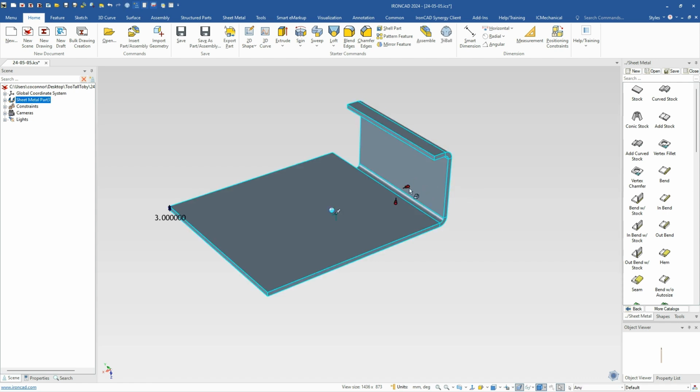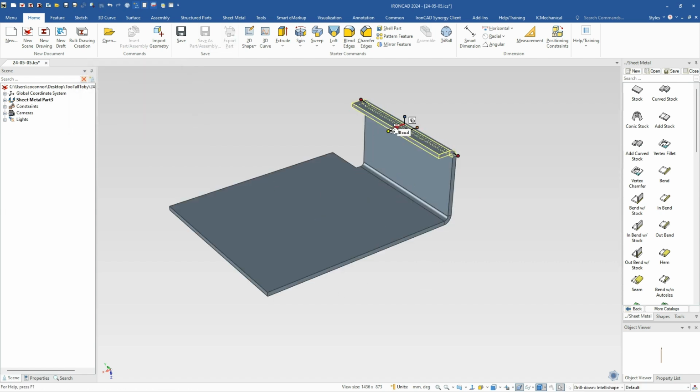It can modify these. So in our case, we want to edit the distance from this guy to the point, which is the midpoint here, and we know that has to be 80mm because it's going to be 160 total in the distance. So now we can come up to this handle, get its value again, same thing, edit distance from point. We'll select that midpoint there again, and in this case, it's going to be 115, so 57.5 is the half distance of that.